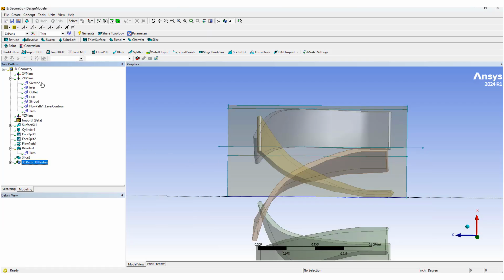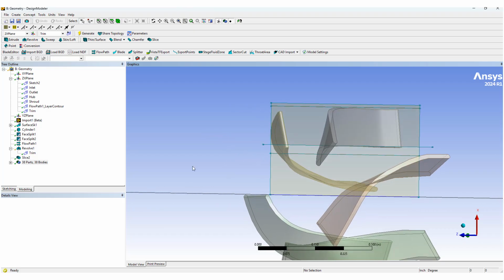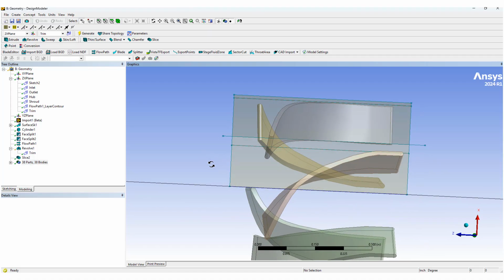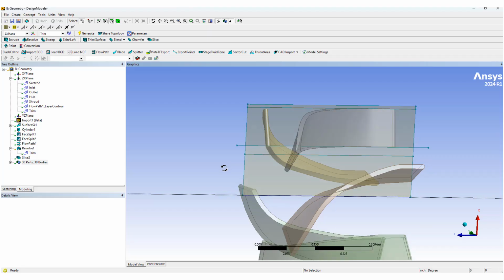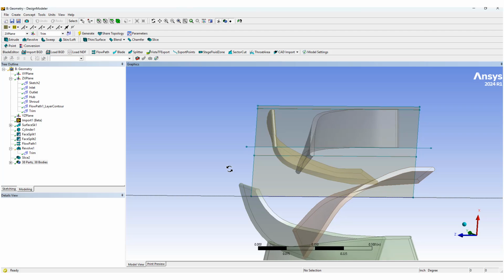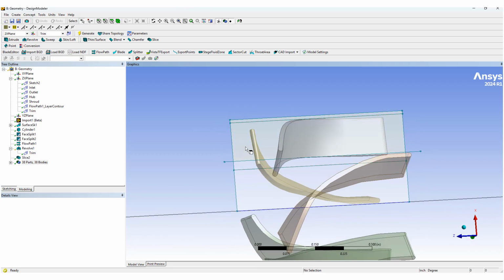So after the slice, what you see here, I kind of highlighted the other geometries. So we have the blades. So ultimately what we try to do is create the blade region with the defined sketches associated with those, and we have of course used just a single blade. We need just a single blade, and we will generate others with a multiplier later on. And now we have the blades, and we will continue with those.